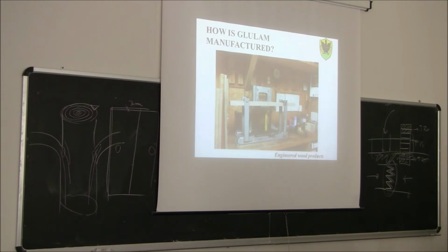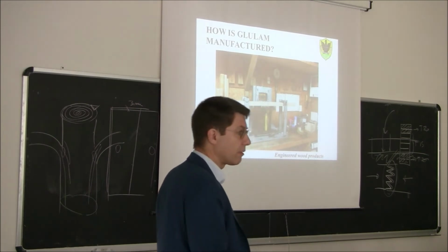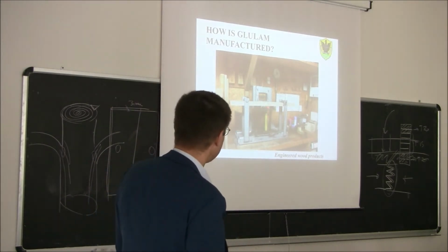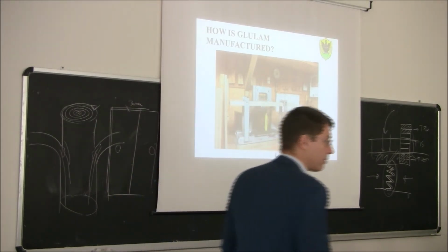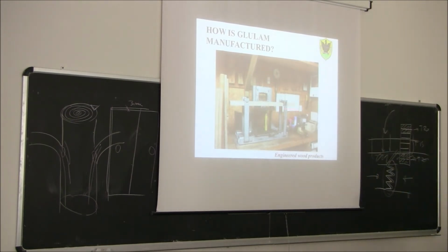As I said before, as a part of the production process, we need to control that the production process works well. And so some of the finger joints, randomly, are tested in bending. This is a destructive test. So in this case, we are not only measuring the deflection, we are actually breaking the finger joint. As you can see here, this is a press.